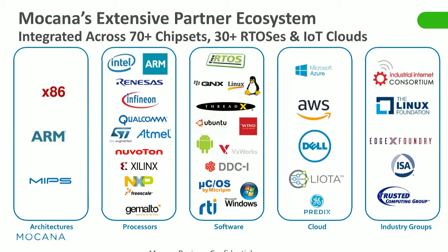Yeah, so we provide integration with various silicon vendors in terms of the crypto functionalities, the trusted functions, and root of trust services that are provided, like TPMs, ST-Safe, Atmel chipsets, NXP, and so on. So we are also supporting MIMS. So any secure element that can provide secure key storage, an enclave for operations that can be performed in terms of PKI. And a lot of times it's really as a key wrapper key to protect the keys, because on these headless devices, you really can't depend on keys being protected on a file system that's not secure.